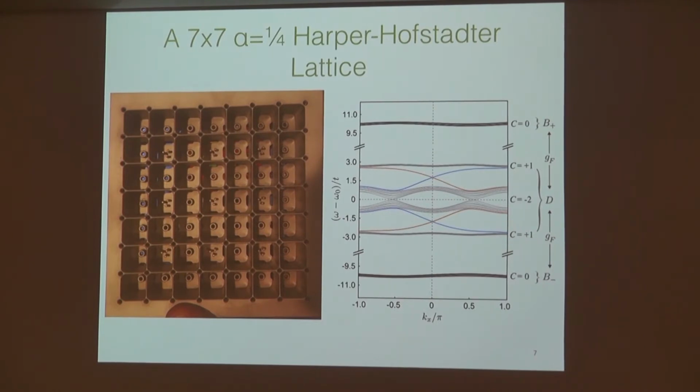Okay? Yes? So if I chain a bunch of circulators in a lattice, would the physics be similar? What an interesting question. I think the fundamental answer is there are ways to put together circulators that give you nearly identical physics. Because, of course, circulators are made of these little YIG spheres, right? The challenge is how to have a circulator that's high Q, or that is to say very, very low insertion loss. So what we've done in some ways, the circulator designs are typically optimized for bandwidth rather than insertion loss. So we've optimized for very low insertion loss rather than wide bandwidth. But yes, you can think of this as a lattice of high Q circulators.